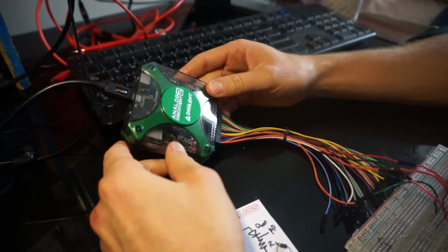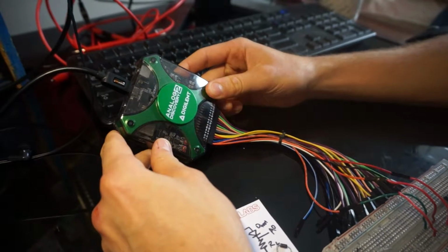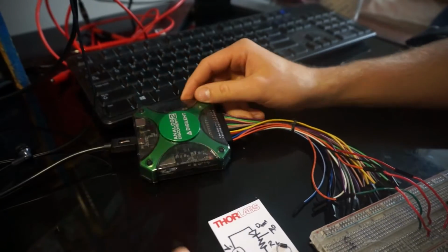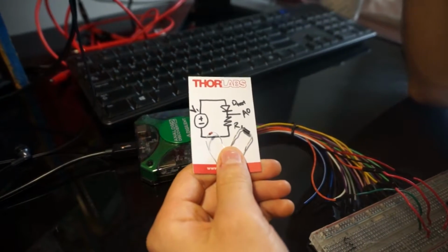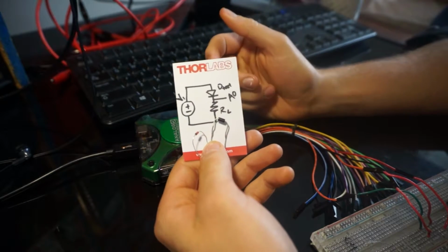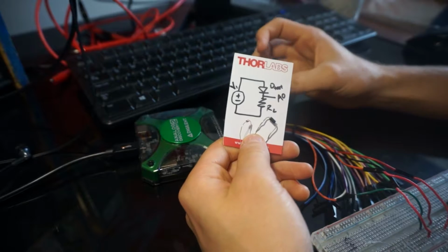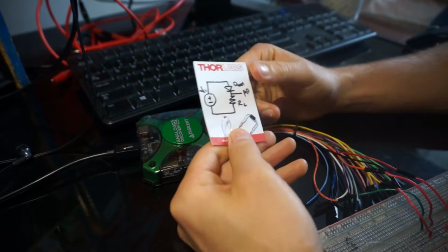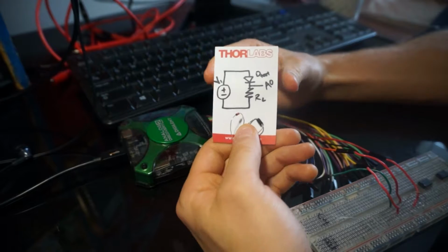So yeah, I've been testing it out, and we're going to show you how to do some work with its API, to write some C programs for it today. And so I guess an easy example to realize that would be, I want to write a script to make some diode curves. So you guys have all seen a diode's IV curve, the current that it passes for a given voltage across it. And so we're going to test that today with a simple circuit.